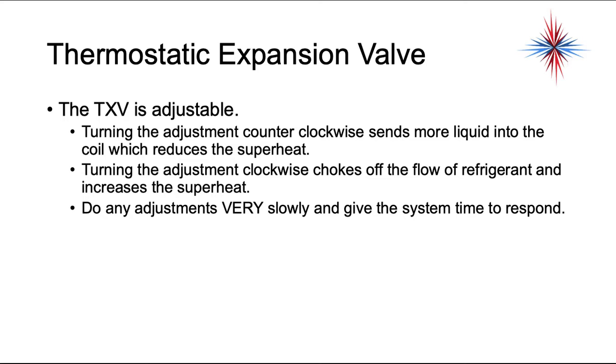Any changes to a TXV are not fast changes. You make the adjustment, usually a quarter turn at a time. You wait 5 to 10 minutes, let the evaporator even out, check your superheat, and then see if the change did what you needed it to do.